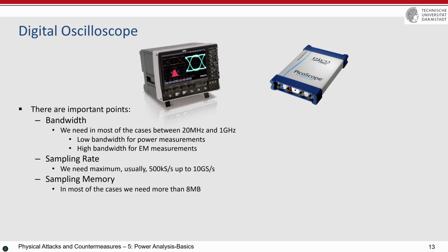Because it should store all these samples at data speed. And of course, SRAM at data speed does not exist. Then they have to use a lot of modules with a small delay and interleave the data which are saved into the memory.